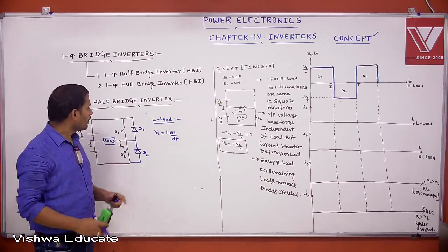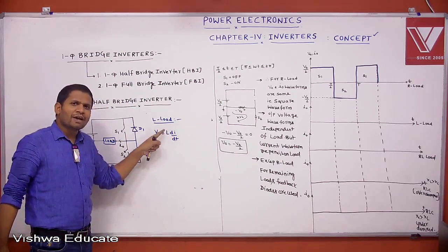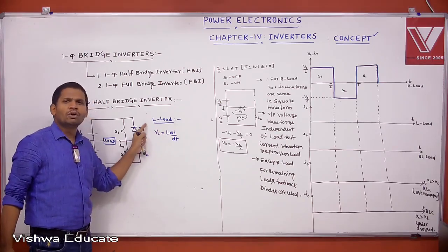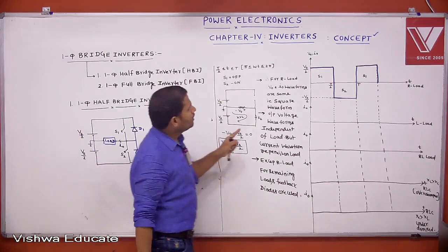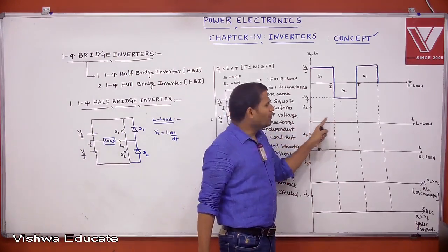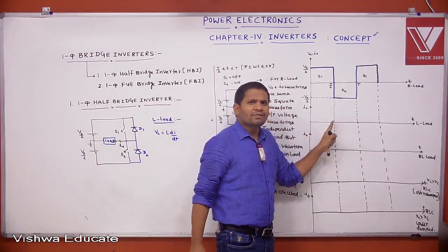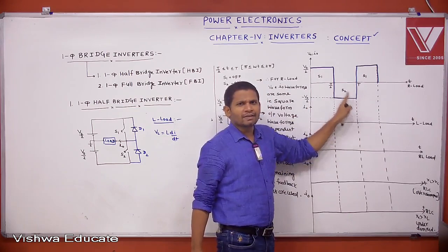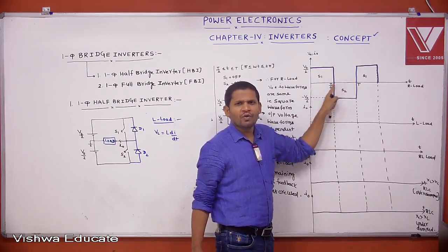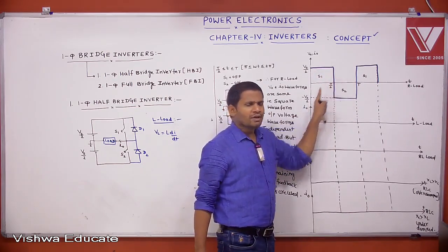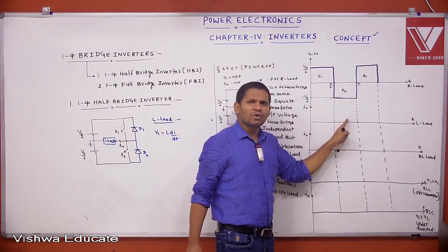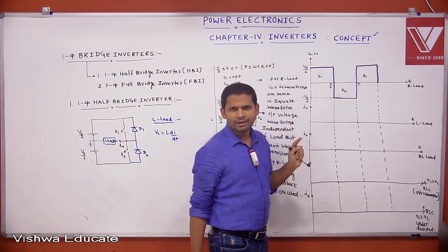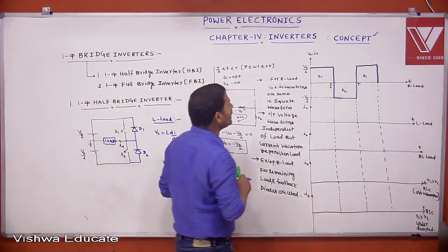That means the rate of change of current through a pure inductor must satisfy the load voltage waveform. For a purely inductive load, if any device is conducting, that device must satisfy the voltage waveform condition. Whatever the load connected, this waveform will not be affected. This waveform remains the same. The device which is supplying the current to the load satisfies this voltage waveform condition.